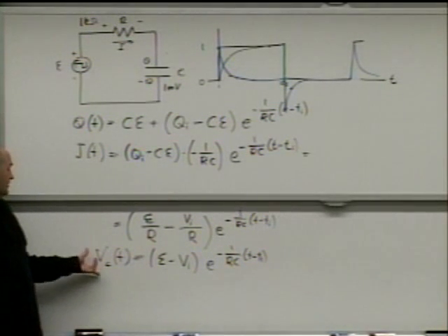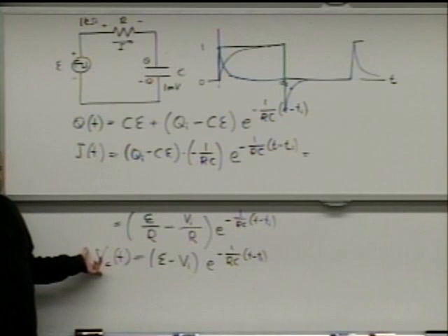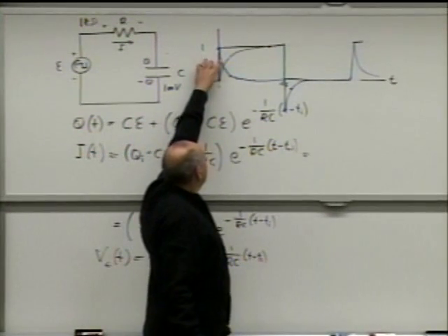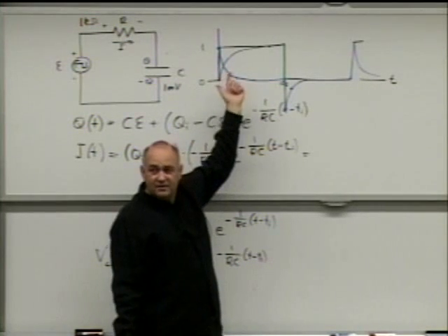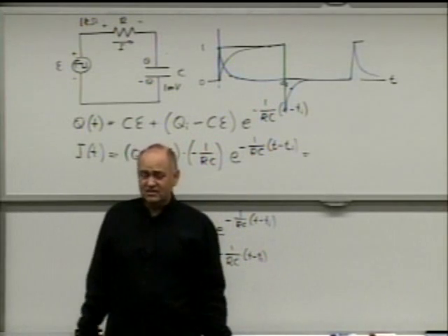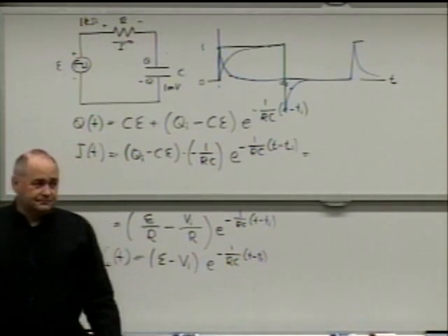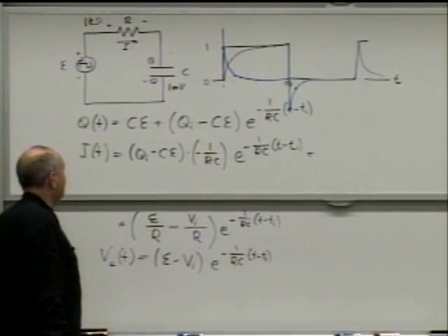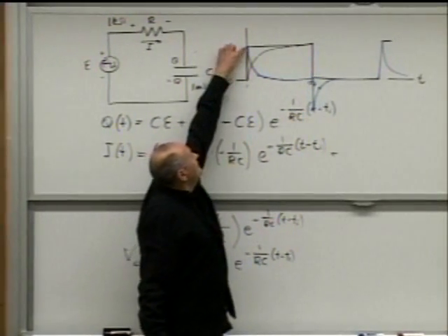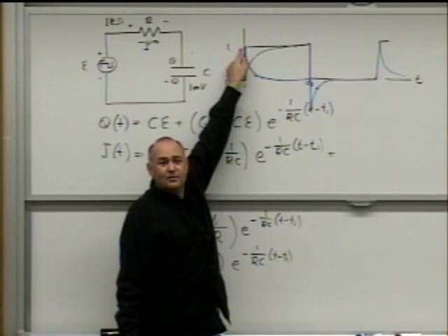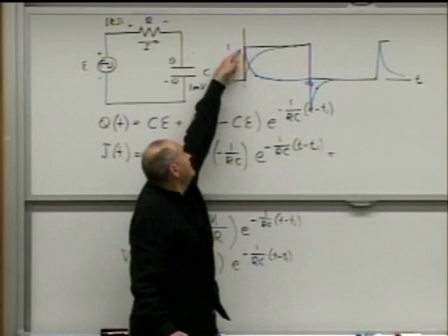So if I wanted to draw this function, how is it going to look like? It's going to be proportional to that blue line, because that blue line represented current. Now I have to multiply this blue line by resistance, and it happened that I picked resistance to be 1 kilo ohm, which means that I have to multiply this by 1 kilo ohm. Recall that this was 1 milliampere. So what would be the voltage across the resistor when that current was 1 milliampere?